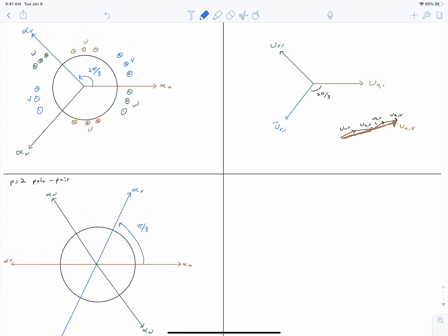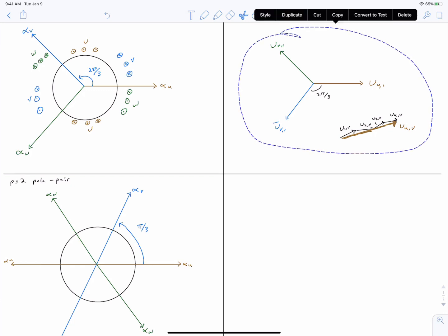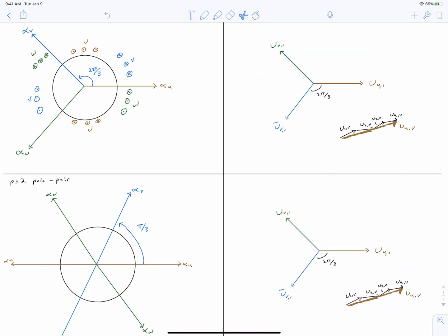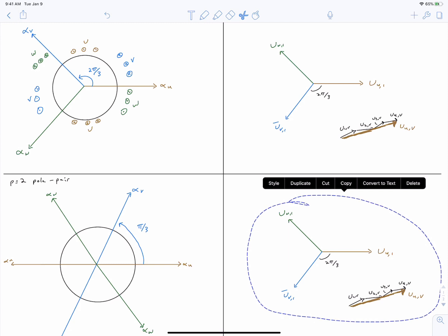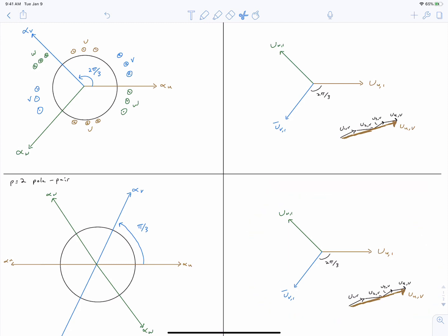And what we expect from our electric characteristics, our back EMF, is exactly what we had for the one-pole pair motor. So our expectations in terms of current linkage change. We want the current linkage to repeat itself more times on the inner bore of our stator, but our expectations from our voltage in time stay the same. We have a certain electric frequency, and we expect that our phases are distributed within that electric frequency by 2 pi by 3 radians. But again, these are electric radians.